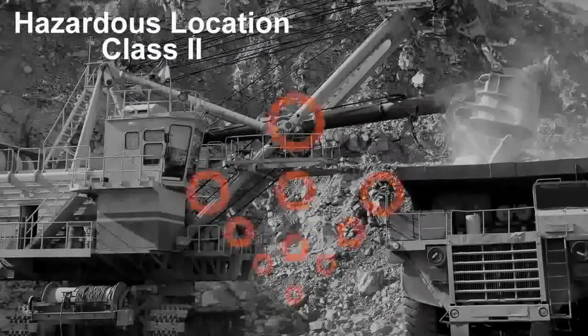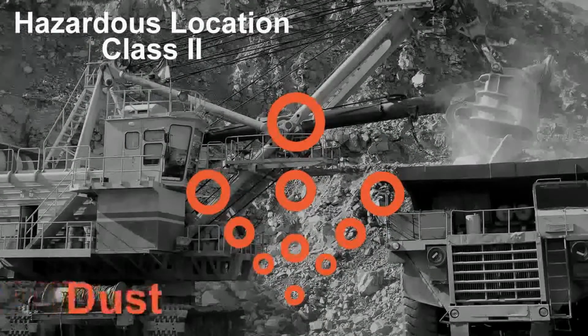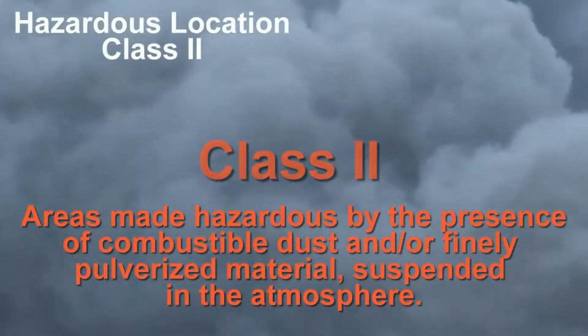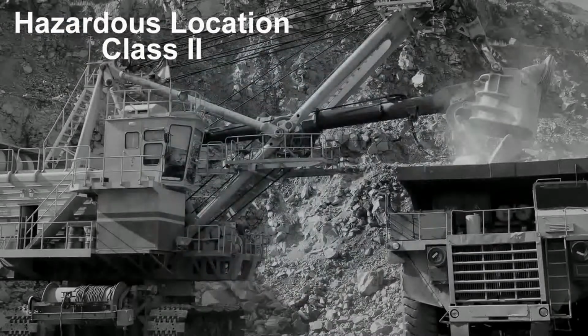The second type of hazard listed by the National Electric Code are those areas made hazardous by the presence of combustible dust. These are referred to in the code as Class 2 locations. Finely pulverized material, suspended in the atmosphere, can cause as powerful an explosion as occurring in a petroleum refinery.